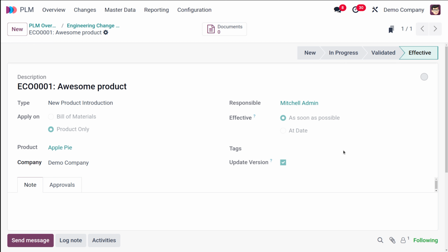So you have the different things like displays the workflow stages defined. Okay, and this will provide a visual representation of the change process. Okay, so this was a change which we applied on a product. So that's how you do it. Okay, you can carefully define the categorized ECO type to ensure efficient organization and filtering. Okay, and there will be a smart button which is called revision, and this is crucial for maintaining a clear history of BOM version. Okay, and ensuring traceability of changes.